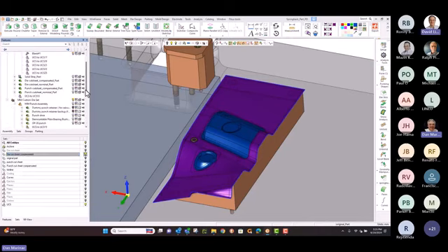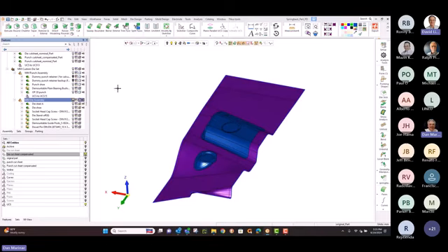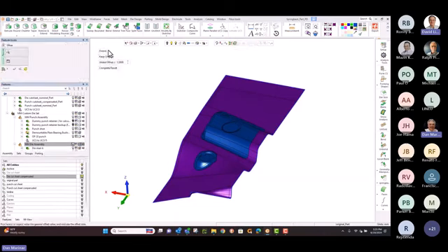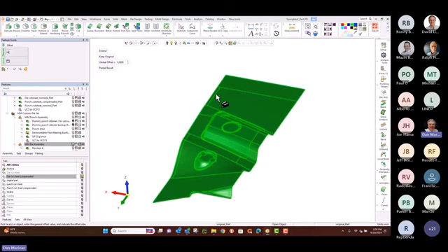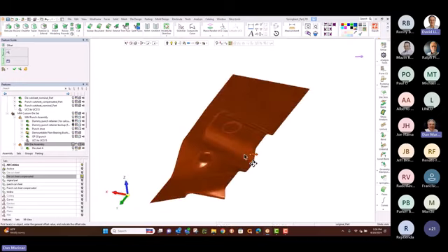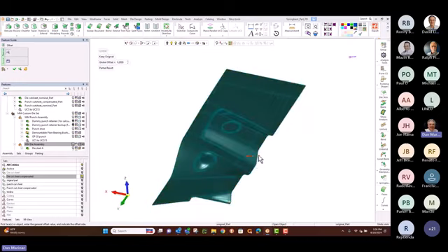So taking this forward, one might ask, well, what about the punch side now? Same process, if you so desire, using a punch cut sheet, or I could simply make one. If I've got that deviation in there or the compensation I need, then it's just a matter of offsetting this to get the opposite side of tooling. So here we're going to do the offset. We'll go the part thickness, make sure we offset in the correct direction, and let it give us that punch cut sheet.